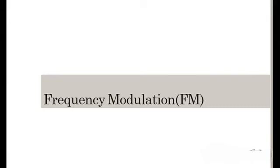systems. It is called frequency modulation, varying the frequency of the carrier in line with the intensity of the modulating signal. The advantage of frequency modulation is decreased noise. We can also reduce noise by increasing the frequency deviation, which brings a significant improvement in the signal-to-noise ratio. It also reduces interference from the adjacent channel through guard bands.